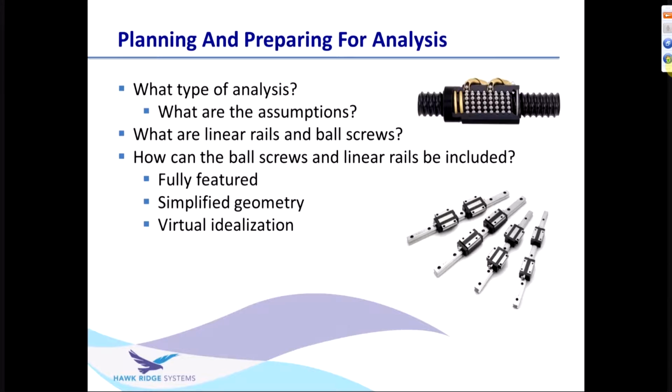So in our discussions with the customer, we decided to go with a linear static stress analysis. The assumptions that go with this include that all materials basically behave linear elastically. Materials are going to be considered as isotropic, and we're looking at small deflections that do not significantly affect or change the stiffness of the structure, and all loads are basically going to be applied slowly, and the inertial effects won't be considered.